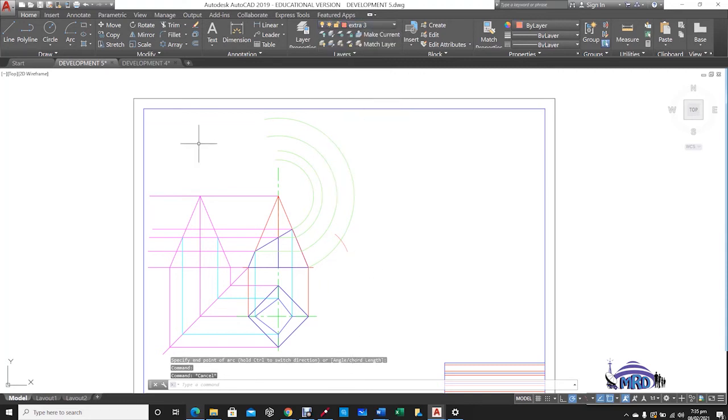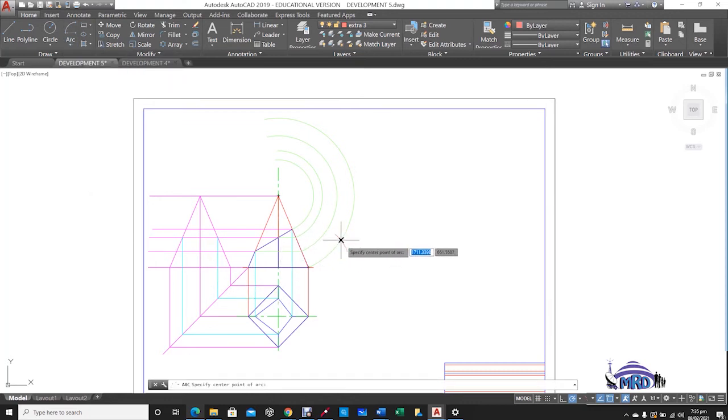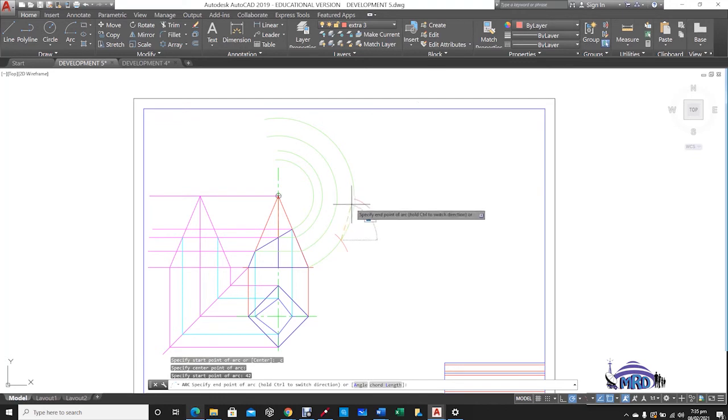Then you know your radius, so you know the curve that you're using. You will plot your second curve again, radius of curve 42, enter 42, and that gives you your second arc, and you continue with this process.